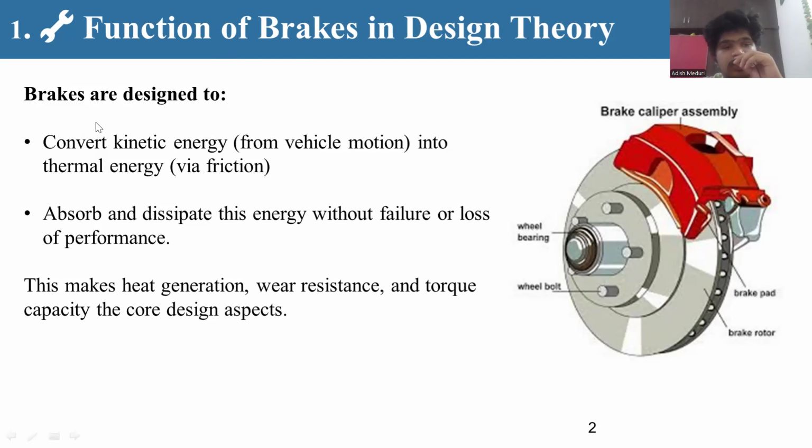So to understand design, first we need to understand what brakes are. Brakes are nothing but that which converts kinetic energy, that is the vehicle's motion, into thermal energy via friction. Absorbing and dissipating this energy without failure or loss of performance is called a brake. This makes heat generation, wear resistance and torque capacity the core design aspects.